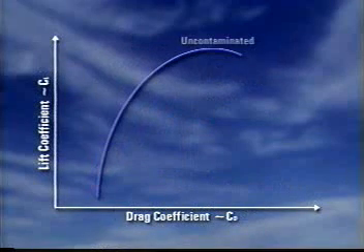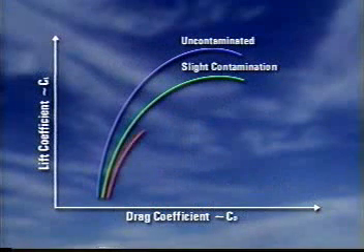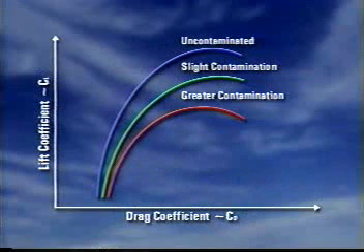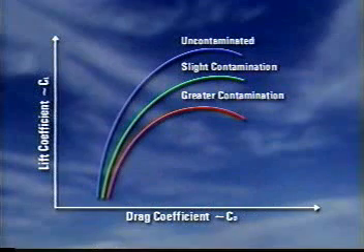Ice causes a similar effect on drag. Drag varies greatly from almost no increase to a more typical 100% increase, resulting from rime ice, and 200 to 300% for clear or glaze ice. The overall effect of ice accumulation on the wing is quite obvious.